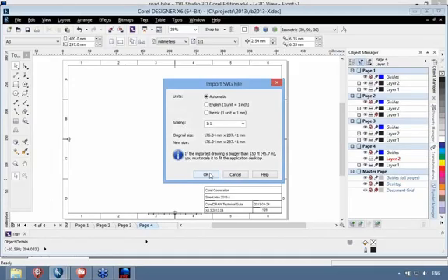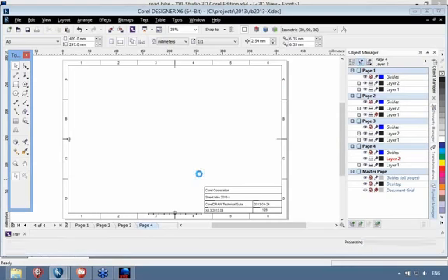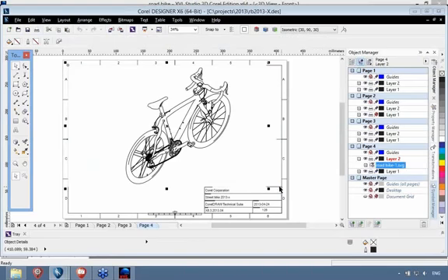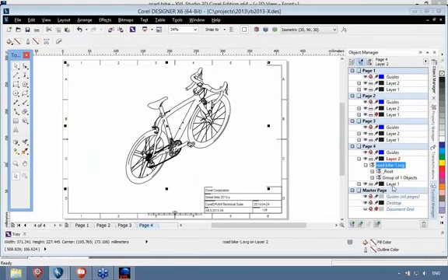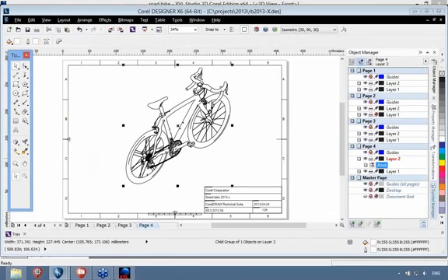So with Corel Designer X6 and the CorelDRAW Technical Suite X6, you can now specify scaling, and with previous versions we had that import that places the imported 3D sourced illustration in the center of the page, and then you need to pick it up, to select it, and maybe reposition, rescale again. So that's now very easy, as you can use the snap items, for example, the snap points, and place it where you want and the way you want. So that's how quickly that can be.